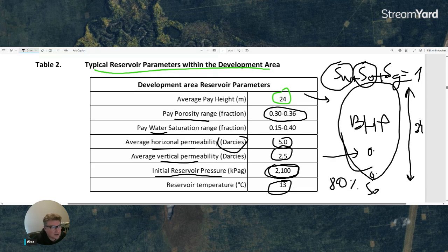You co-inject with methane, so natural gas, right? And that is maintained in the gaseous phase in situ. So this way, it doesn't condense right away like steam or water, or not right away, but at the same rate on the vapor pressure curve. And it's able to maintain the steam chamber pressure.